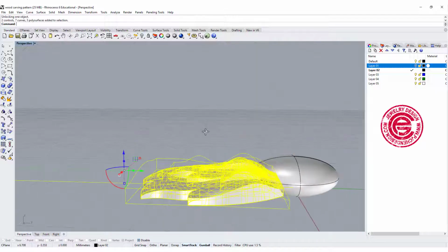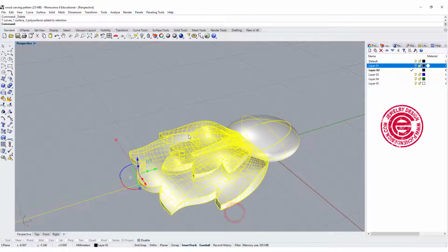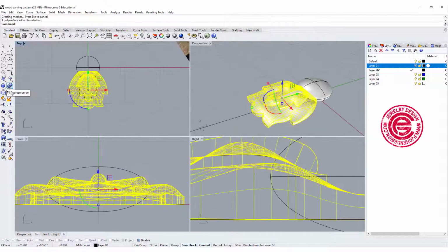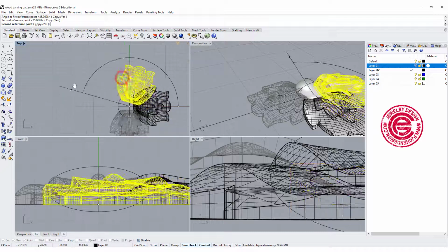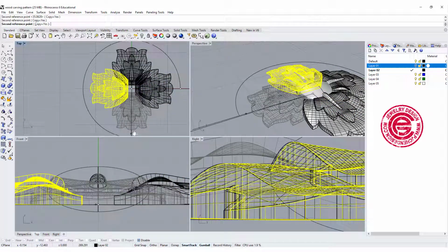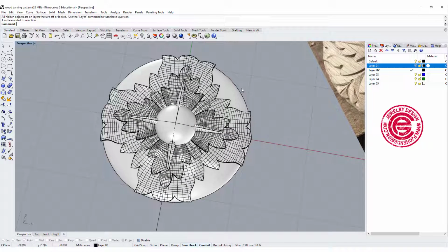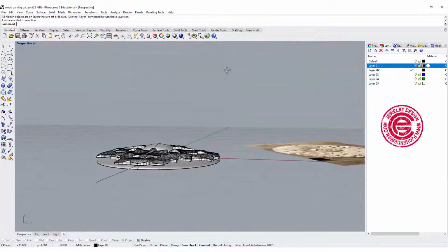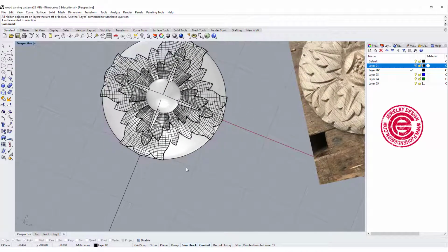If that is something that you like, you can go ahead and delete this box and the box over there, and let's go ahead and boolean the leaf. Use the rotate copy equal yes. Let's rotate it 3 more times. And we want to call out the original round surface. So you can do the same thing to fill up the design in the center.